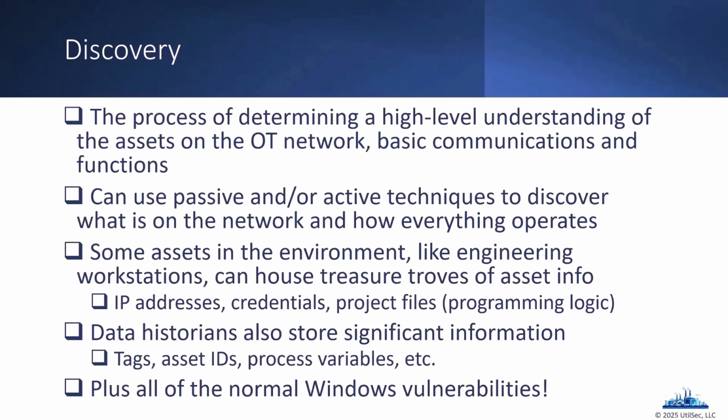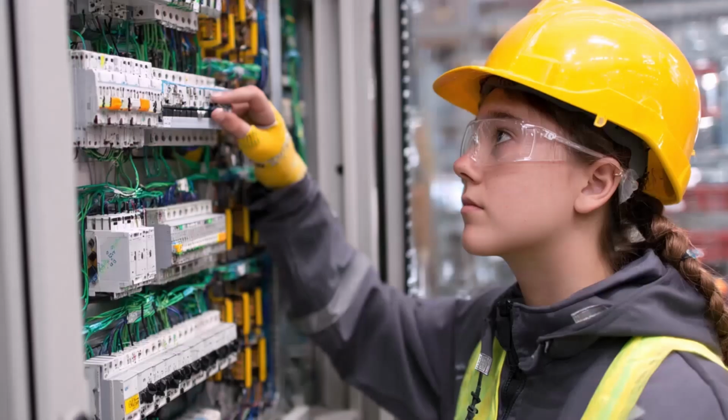And then we do mention a lot of these systems, right, when we talk about engineering workstations, right, data historians, they're all running on Windows. So they have all of those Windows vulnerabilities that make it really easy to take control over these assets and gain access to the data that's stored on them, especially if those assets aren't being patched on a regular cadence, or every once a month, even though they should be. Are we patching PLCs once a month in environments? No, of course not. Maybe not for years, if that at all.